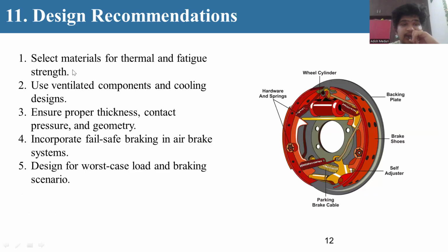Design recommendations. Select material for thermal and fatigue strength. Use ventilated components and cooling designs. Ensure proper thickness, contact pressure, and geometry. Incorporate fail-safe braking in air brake systems. Design for worst-case load and braking scenarios.